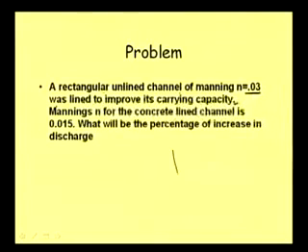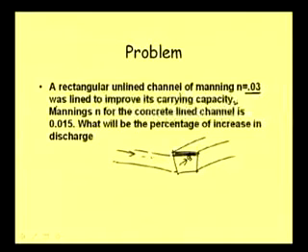In fact, suppose in a channel, say this is the channel, we have some Q, some discharge flowing, and we want to drain out the water quickly, because if we cannot, the water level here will rise. Then suppose another sub channel is joining this channel, the water flowing there will also be affected, because once this water level rises, from here you will not get a hydraulic gradient.